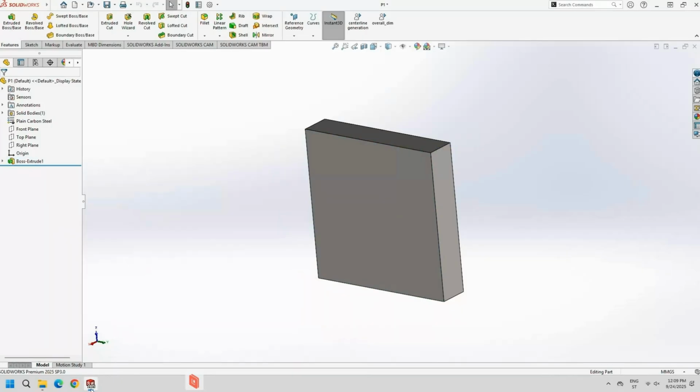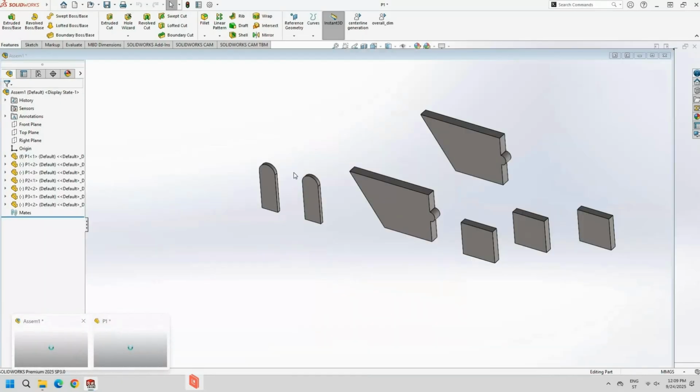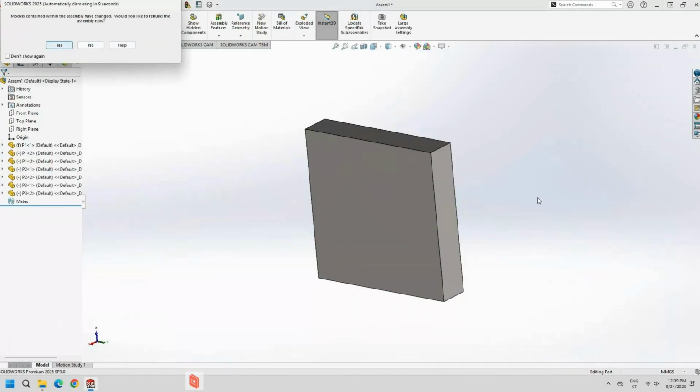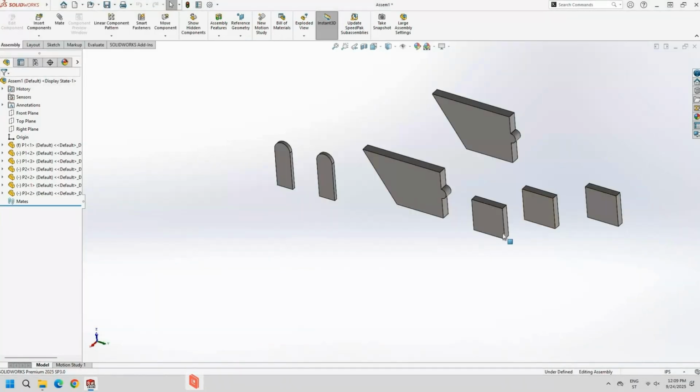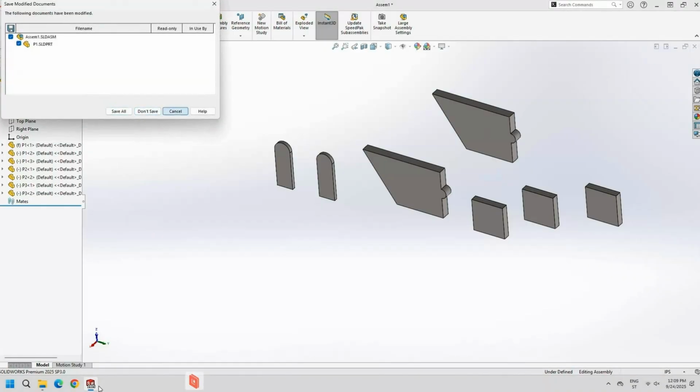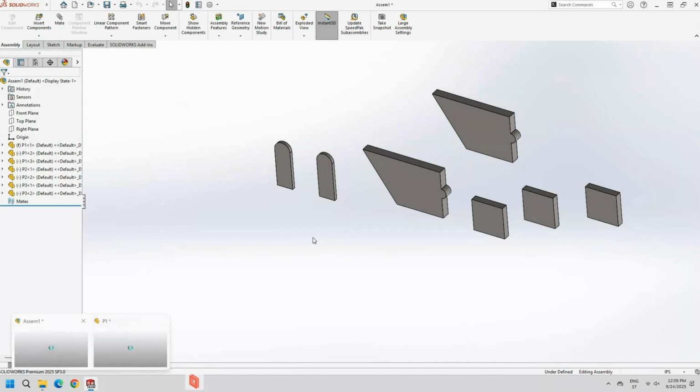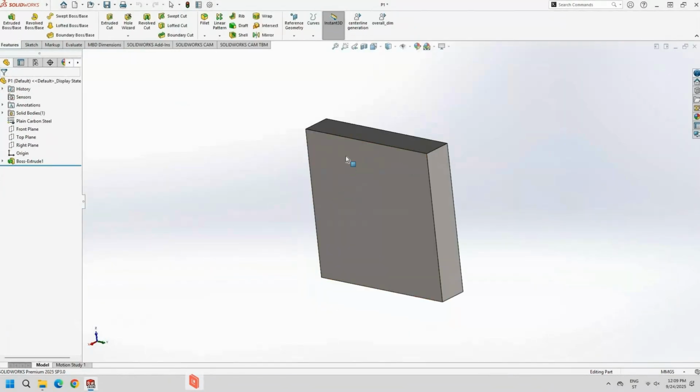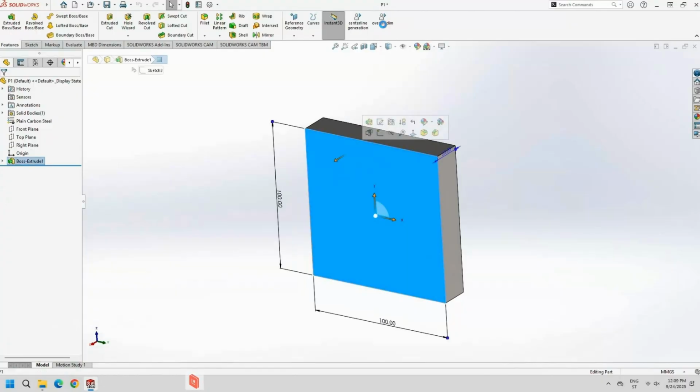Also, another thing that's important, if you want the quantity from an existing assembly, you have to have the assembly opened up in the background. Now, the hierarchy here doesn't matter. You can have this part on the main assembly level or on a sub-assembly level, and it will count them all. Now, all that you need to do essentially is just select the face and run the macro.